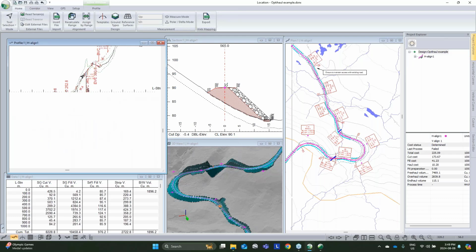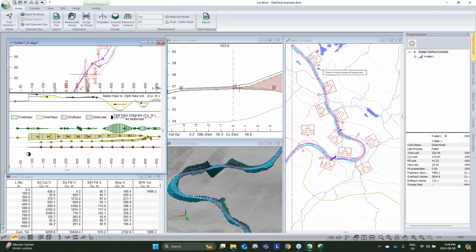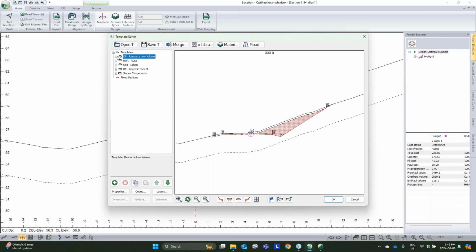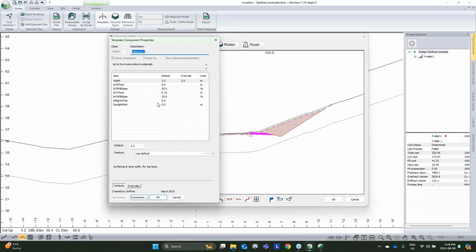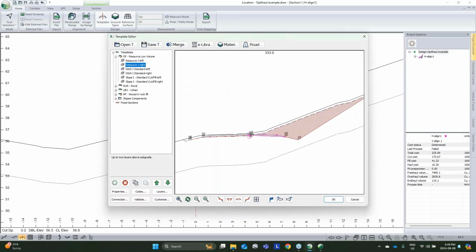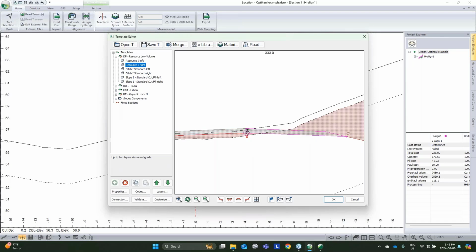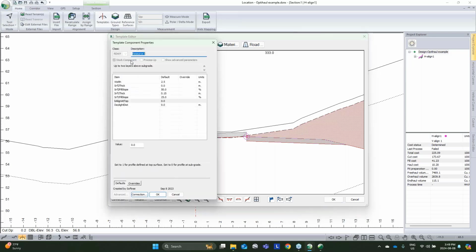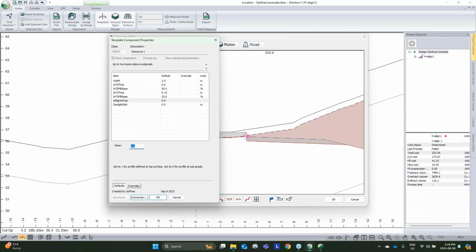Okay, well, that is a dealer's choice. So it's just up to you, however you have it set. If I go into my templates, I've got my default template applied to this location. I have my template, and we can zoom in here, and we see the template is attached to my center line, so that's subgrade. Now, it doesn't have to be. If we'd rather that at finished grade, we've got B align at top. It's just a matter of changing that template here, and we can do the same on the other side, and away you go.